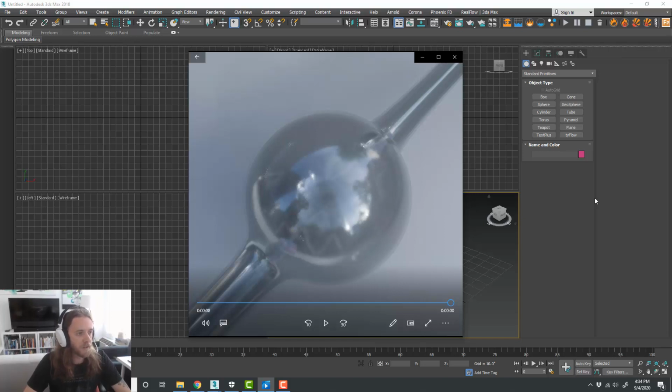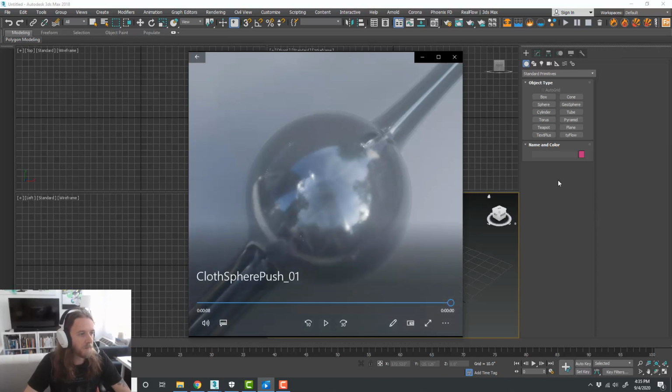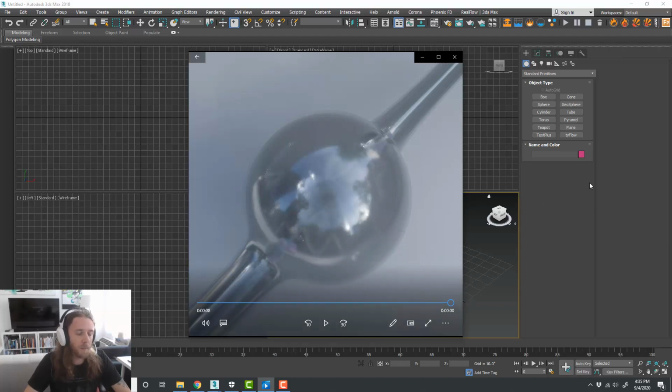It definitely takes up a lot of resources on your graphics card. So if you have multiple graphics cards installed, you can assign one particular card to do the calculations and have another one just for navigating your model environment and stuff. So we'll maybe take a look at how to set that up.